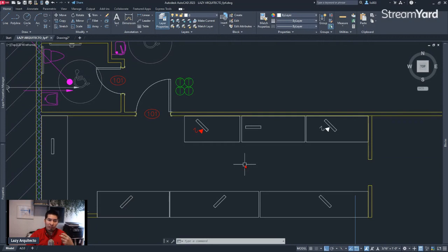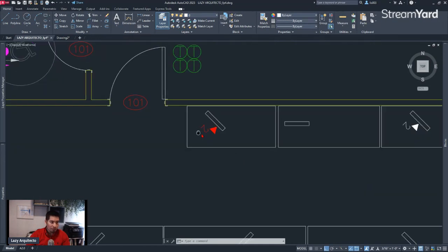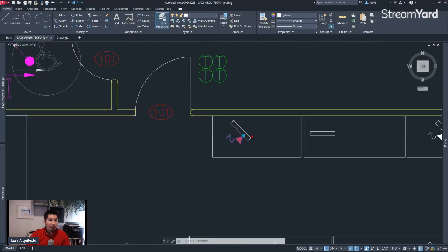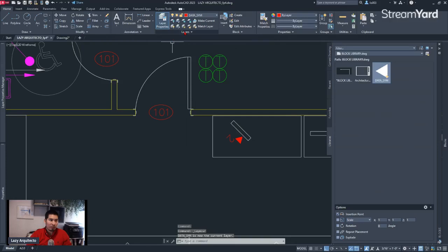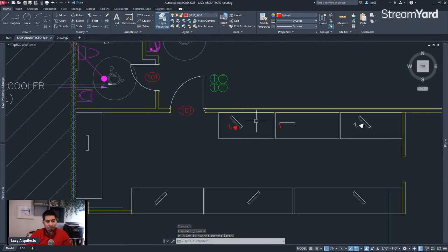So we wanted Autocad to avoid asking this question and simply put the number 2 on it. So the way we did it was, of course, first let me change the layer to make it current over here, so that way when we inserted the block it will come on the correct layer.